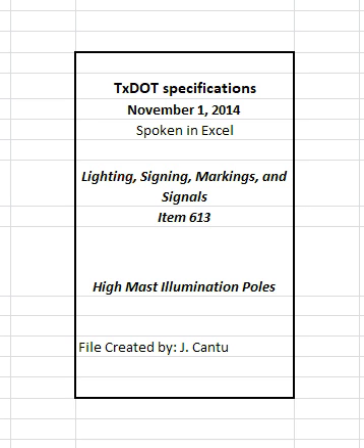After the high mast pole has been plumbed and all nuts are tight, tack weld each anchor bolt nut to its washer in 2 places and tack weld each washer to the base plate in 2 places. Tack weld in accordance with Item 441, steel structures, the AWS D1.1, Structural Welding Code Steel, and the requirements of this item. Never weld components to the bolt. Repair galvanizing damage on bolts, nuts, and washers in accordance with Section 445.3.5, repairs, after tack welding. Do not grout between the base plate and foundation.